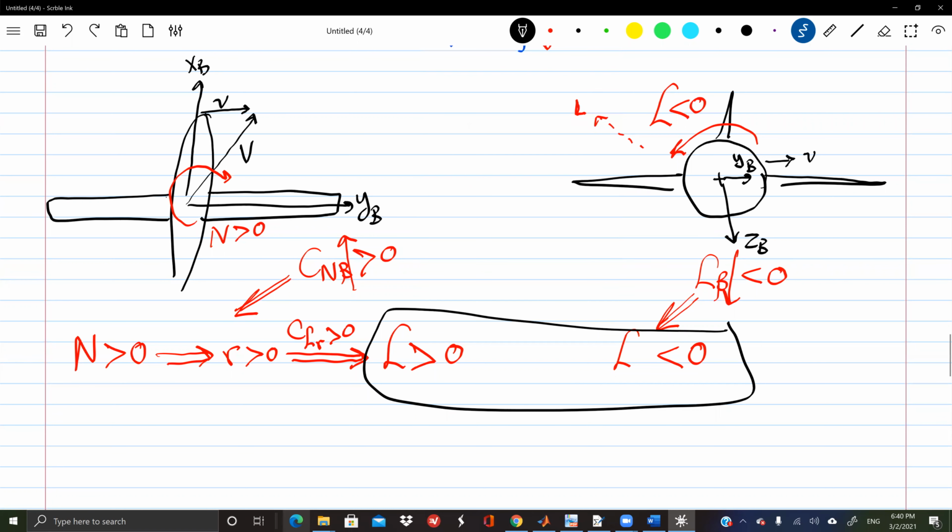One is large and one is small. So this one will outweigh and will overcome, and the airplane eventually will roll to the right, in addition to yawing to the right, which means that it will depart. It will go into a turn, actually a steep turn. When you go into a steep turn without manipulating your lift, you will lose altitude, so you'll go into a spiral down.